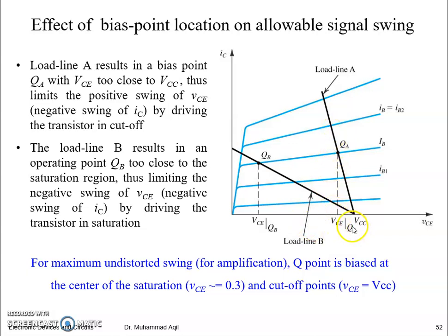But as soon as the negative phase of V input comes, AC VBE decrease will decrease the total VBE. That will decrease the total IC, corresponding to the animations shown in the last slide. So that decrease in IC will be providing an increase in VCE. But this VCE increase has a limit to this VCC. It cannot provide more than these voltages, the VCC.